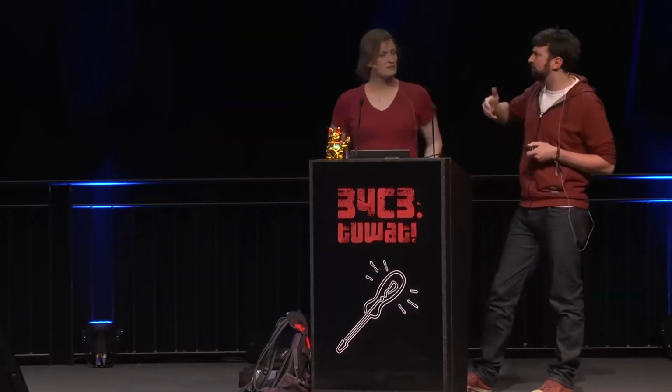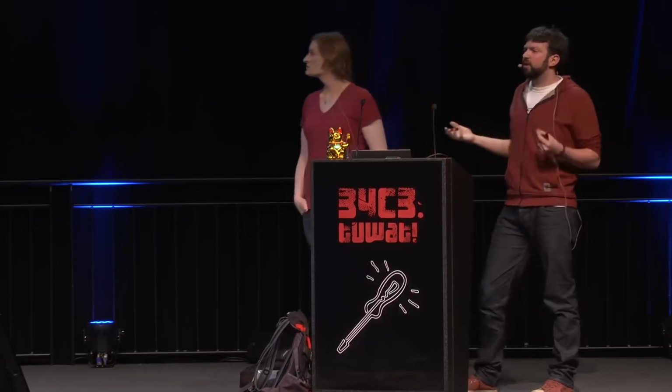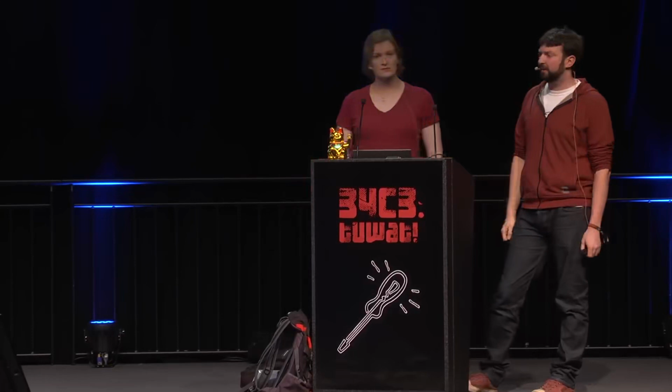Yeah, and to a certain extent, you might want to do that because you might want to apply power to the device and then wait for it to come up before you start trying to talk to it over USB and things like that. Those I/O lines don't have to be complex chip-to-chip interfaces. You can just hook into one of the LEDs and say, well, when this LED comes on, I know it's booted.